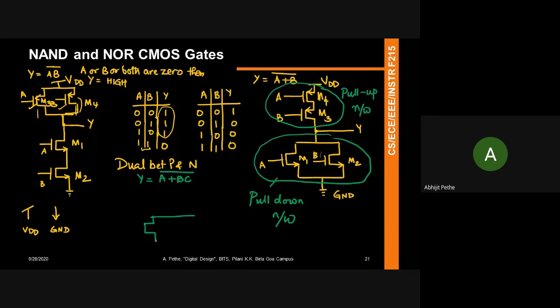So again, remember, this was how you did A. So let me use the other convention for the gates. Right, so this was how you designed the pull down network. So this was your Y. So again, A is in parallel with B and C. So here A goes in series, right? So this becomes A, and then you have a parallel combination of B and C, and then you'll have the supply voltage there. So remember, whatever becomes series converts to parallel between the duals.